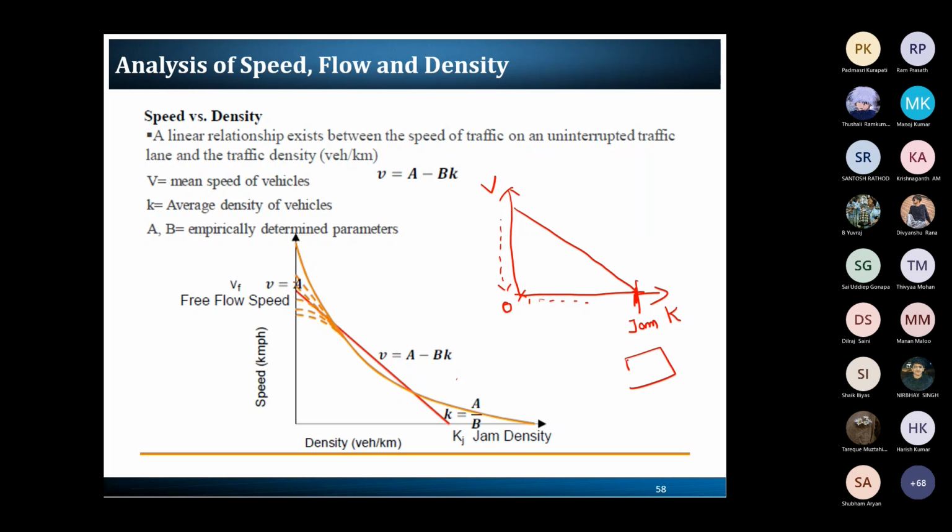The vehicles are stopped in the given corridor without moving due to the jam, and are not getting an opportunity to move. Ultimately the speed becomes zero. When we try to achieve the maximum speed, there are very few vehicles, maybe only one vehicle moving. That speed is considered the free flow speed. So this is the way we can explain the relationship between speed and density.